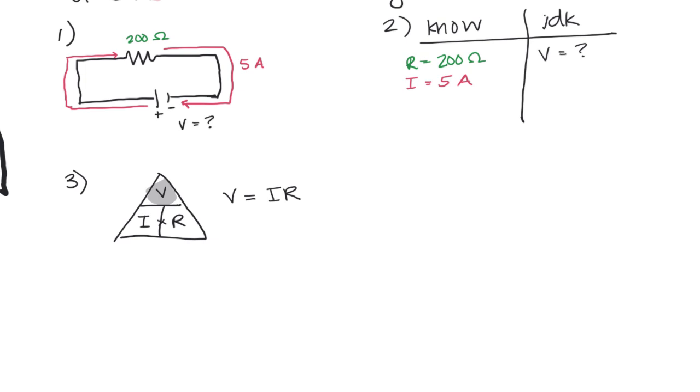So moving on to step number 4, I'm just going to rewrite our equation here. V equals IR. I'm going to rewrite V again to indicate we do not know what that is equal to yet. We can plug our number in for current, right? We do know what current is equal to. So I'm going to write current is equal to 5 amps, right?